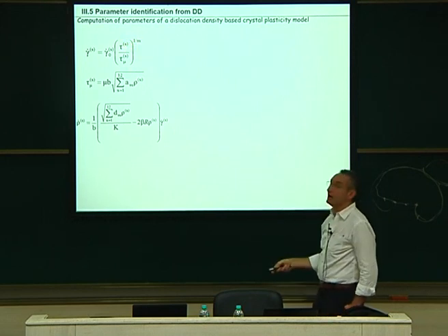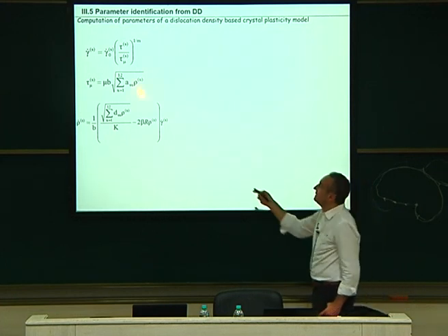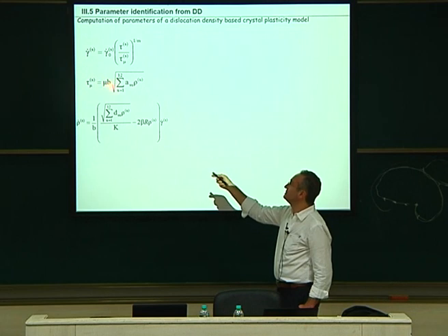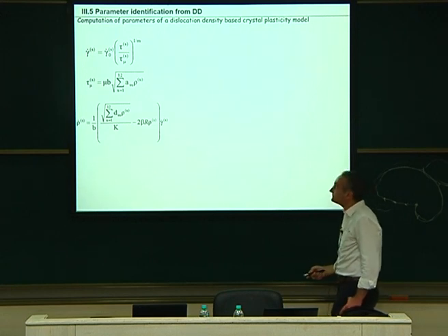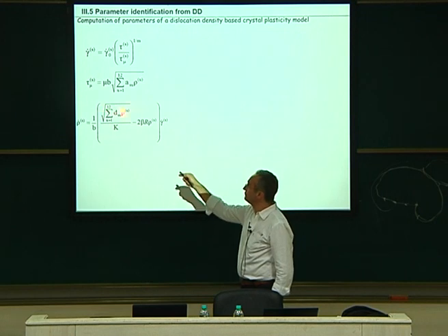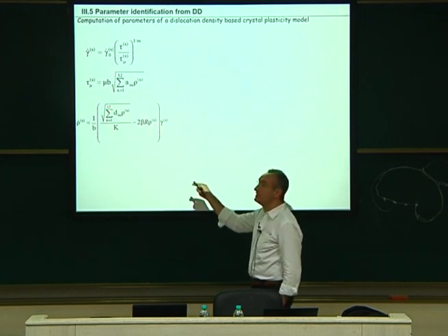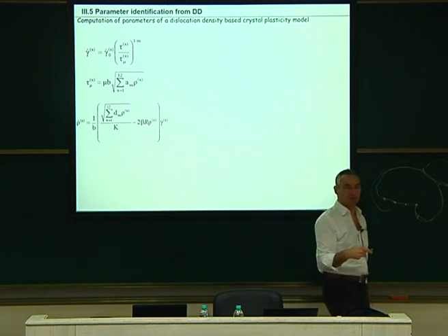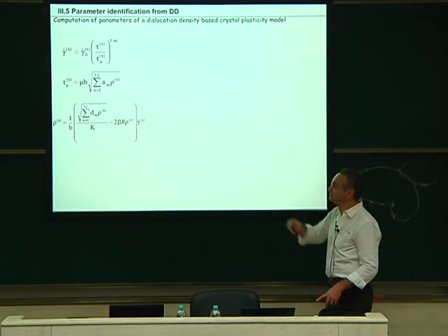And here is a critical isotropic hardening. Remember that this was isotropic and not kinematic. And this isotropic stress is changing with the dislocation densities on all the slip systems, possibly the 12 of them. And this dislocation density can evolve with a production term, so you have more and more dislocation density with the strain, minus an annihilation term that occurs when two dislocations annihilate when they are too close, inside this radius here.